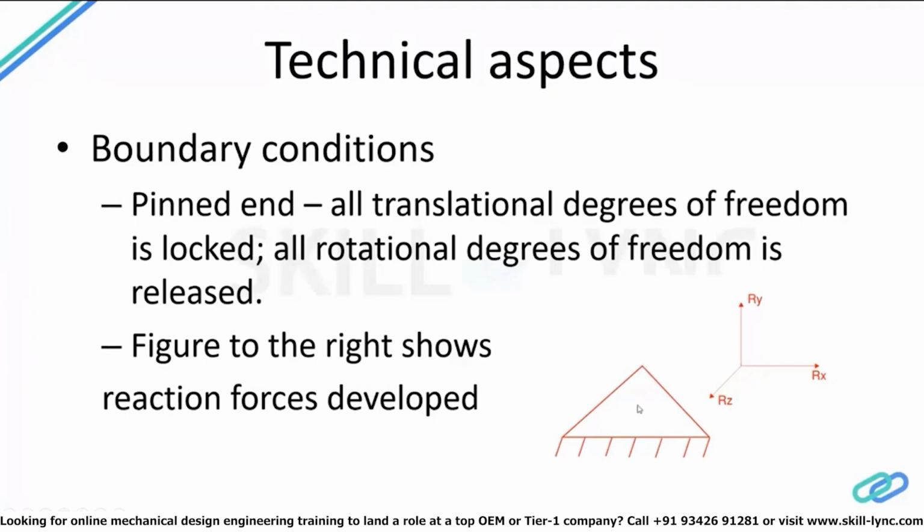A real life example of this support would be, say, a steel beam to a steel column connection, which is a typical shear type connection. In that case, the kind of support that qualifies is a pinned support, wherein that shear type connection prohibits movement of that beam at that end in all three directions, but still allows rotation of that joint. So it's not prohibiting any rotation of the member about the joint, only the translational degrees of freedom are restrained. That's one example.